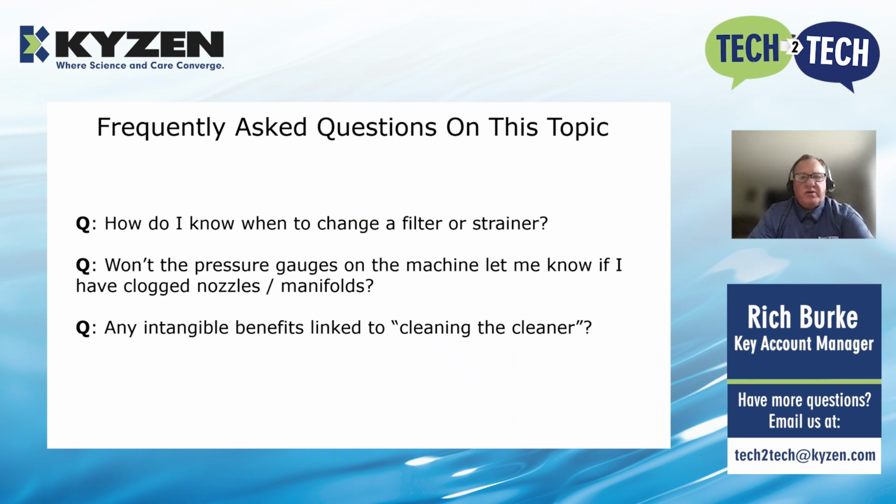So we'll end with some frequently asked questions. First, how do I know when to change a filter or strainer? Well, like I say, follow the instructions from our equipment supplier. Obviously, inspection is a part of it, or visual inspection is a part of it. This can be done off of timers or run time on the equipment.